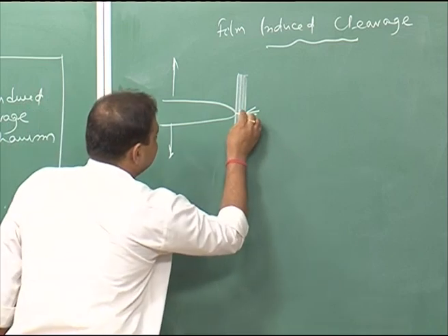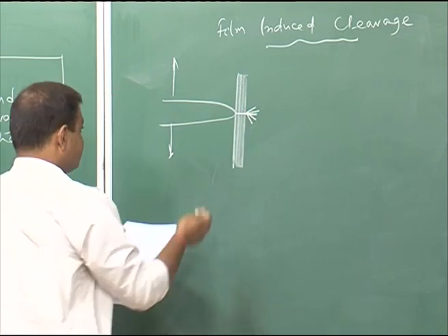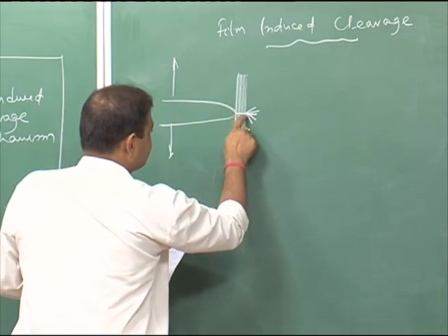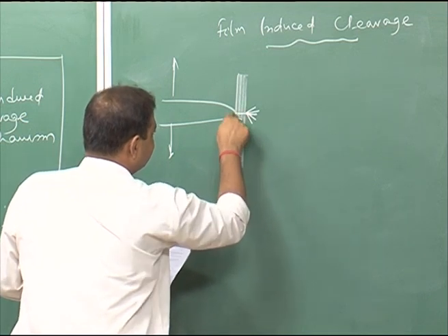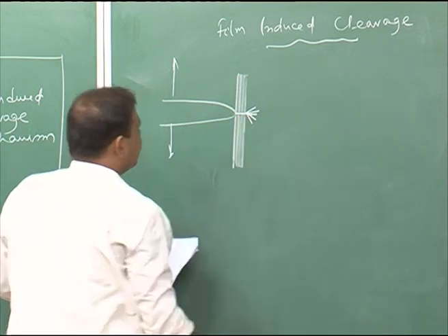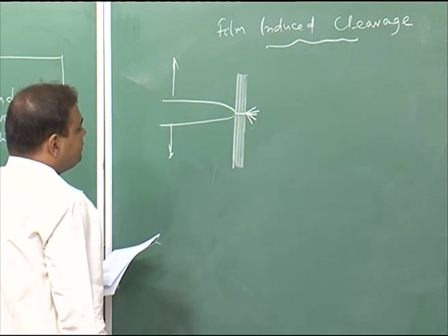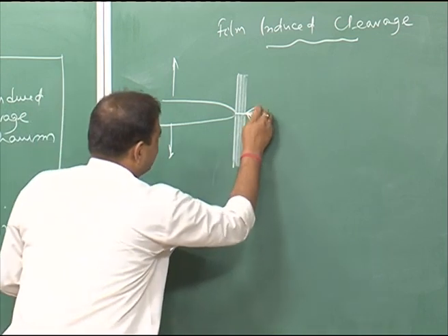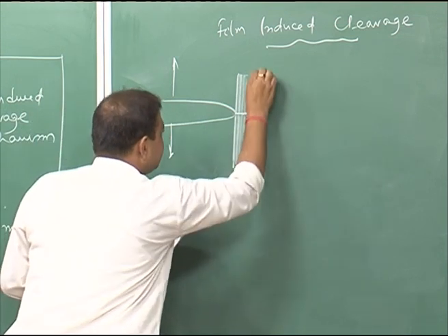So, here the fracture is happening in the film, and that sharp nature of the film can also get into the adjacent volume of the metal, and then the brittle crack propagates a little bit in the metal, and here it stopped again.